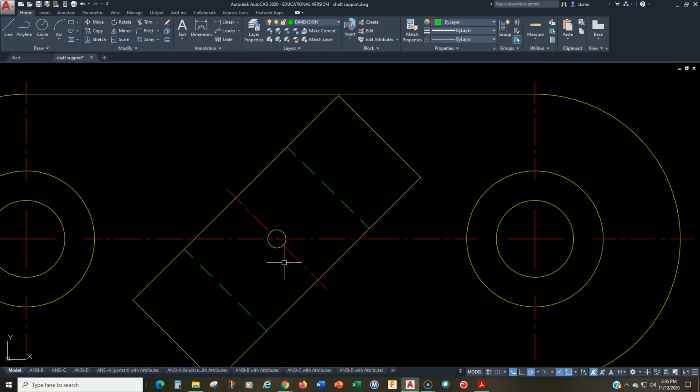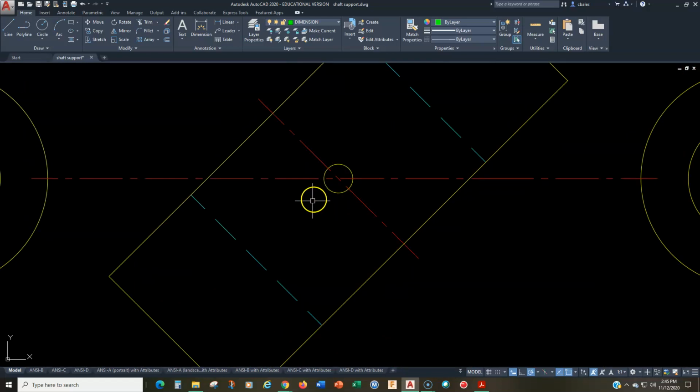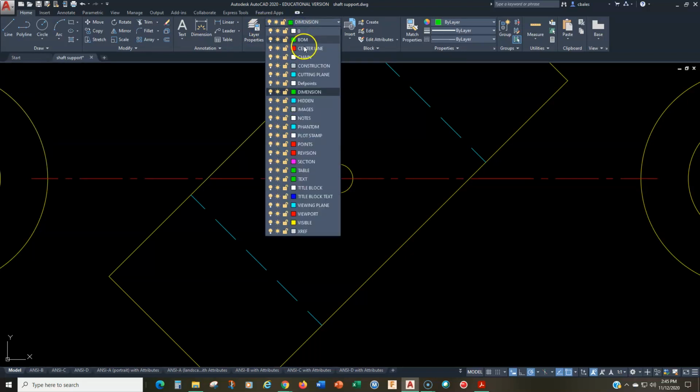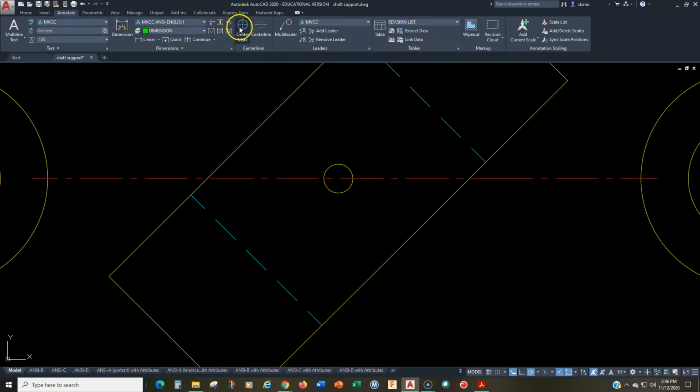First of all, in preparation for this, I want to create a center mark on this, but I don't want a center mark that's just going to be a vertical north, south, east, west center mark. I need to rotate the center mark so that it is aligned with this whole feature. Let me show you. I'm going to get rid of that. Let me go to the center layer, and we'll go to annotate, and we'll choose center mark, and we'll choose that feature right there. Now you notice we get a double line right there, which is not good, but this isn't the orientation that I want.